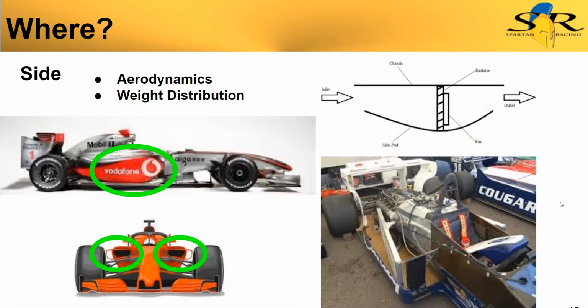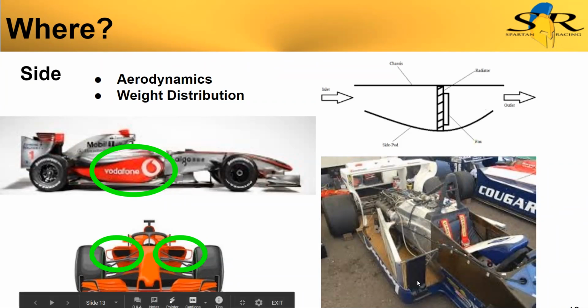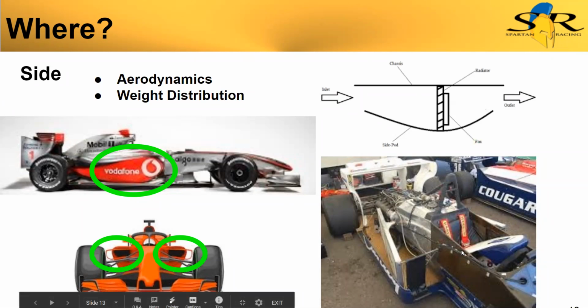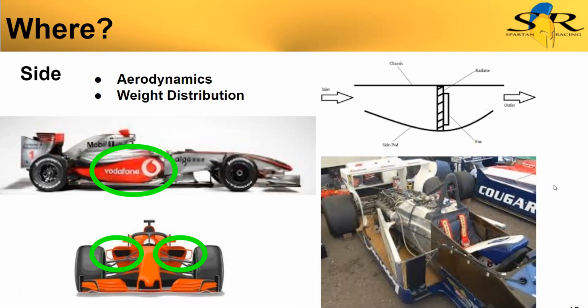Because of that, there's the balance of, all right, we're minimizing drag because we have this small opening and we're pretty narrow, but we have this massive radiator, and it's going to be a lot of weight because maybe we're not using our air efficiently. Whereas if we use more air, there'd be more drag, but we could use a smaller radiator and there would be less weight. Those are the kind of optimization decisions that have to be addressed for sure.